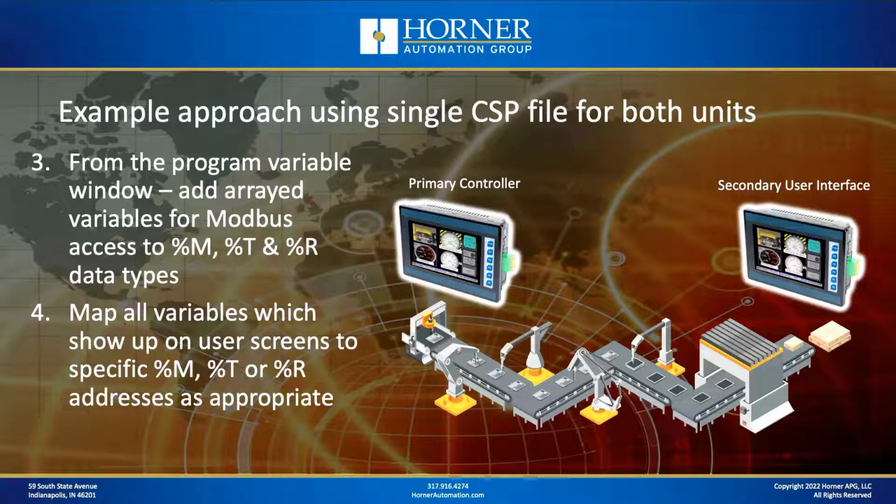Next, the example I'm showing you is going to be variable-based logic. Now you could do it in register-based logic, but I'm showing you how to do it in variable-based logic for this part of the example. So in variable-based logic, when we edit our variables, we use the program variable window.